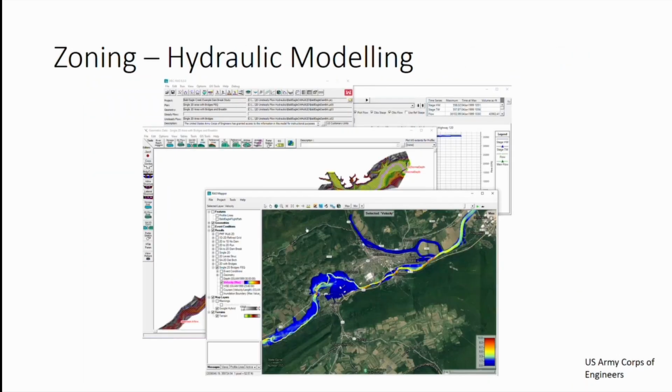There are so many numerical tools out there that can be used in delineating the flood, and one of them is the HEC-RAS, which is used predominantly in the industry. There are also tools like 2Flow, Mike 21, Mike Flood that can also be used. So typically what is done is to set up a computation mesh to solve the shallow water equation as the design flow is being routed through our study area.